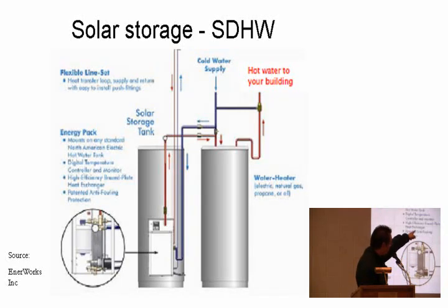At the top, you see a couple of bypass valves. So you can actually, if you were to shut those off, isolate your solar system entirely. If there's any type of issue or you're going to be doing maintenance on the system, you can isolate it from your existing hot water heater, so that you won't be without hot water if there's ever a problem with the system. Next slide, please.